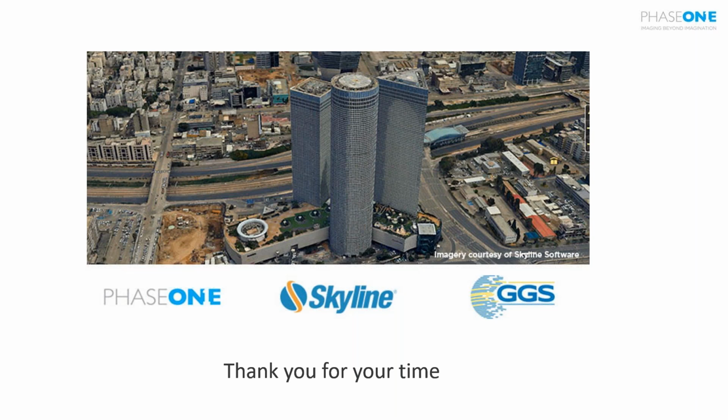And then the next question: can PhotoMesh extract water vectors? Well, if you digitize it inside the software, you can export it to a shapefile, but we don't extract it automatically. And then, can DSM files be edited to smooth out irregularities?